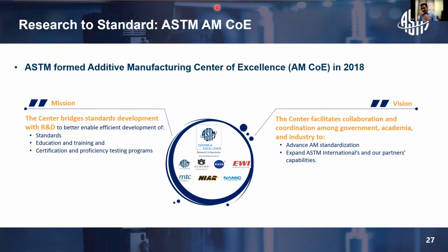We say there is a variability with a single part, and now additive manufacturing is used as a technique for mass production. But now we cannot simply rely on one part, and we cannot just focus on certifying one part. So we have to go for certifying more parts at a time. We need to qualify more parts at a time. So the recent concept is called part family.